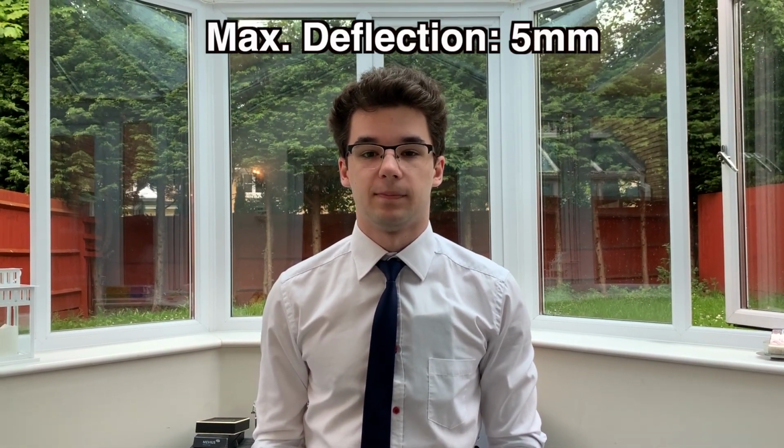As the blade was smaller, the TSR needed to be adjusted so the angular velocity does not go over the maximum value of 3000 RPM. A TSR of 3.5 was picked. Ultimately, however, a TSR of 4 was predicted, given the likelihood of an underestimate from previous year's results. Using bending theory, a maximum deflection of 5 mm was calculated.